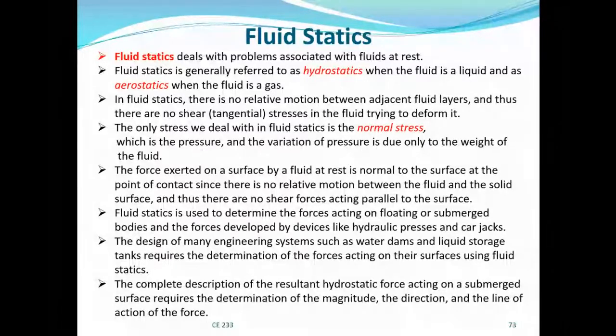In fluid statics, there is no relative motion between adjacent fluid layers, and thus there are no shear stresses in the fluid trying to deform it. Because the fluid is at rest, there is no motion between adjacent layers. If there is no motion, then there are no tangential stresses. But normal stress exists. The only stress we deal with in fluid statics is the normal stress, which is essentially the pressure.